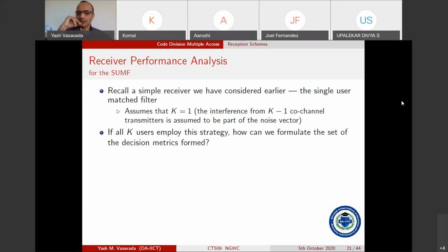So that R will be W, I mean W Hermitian. Like if y is equal to RW, then R is our W Hermitian. Yeah, okay. So k is 1, that each user is thinking that k is 1. The R will be a scalar, so it's just division of that. The received signal divided by R will give you the estimate. Yes, but what is R now?